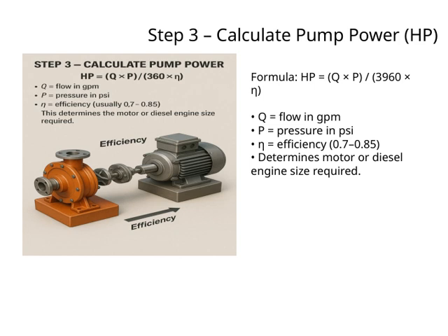This calculation is crucial because it helps us determine the size of the motor or diesel engine needed to power the pump effectively. By understanding these values, we ensure that the equipment is properly sized for the application, leading to better performance and energy efficiency. So keep in mind, the more accurate your flow rate and pressure measurements, the more precise your horsepower calculation will be, ultimately guiding you to select the right motor size for your system.